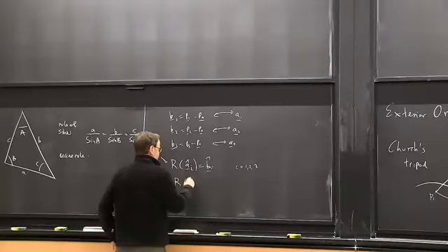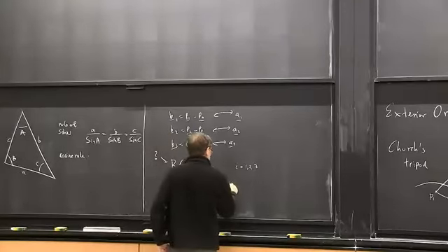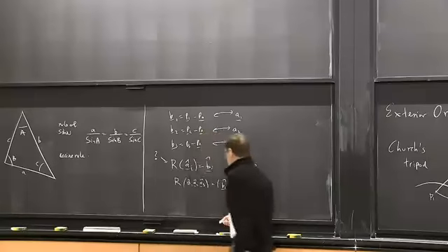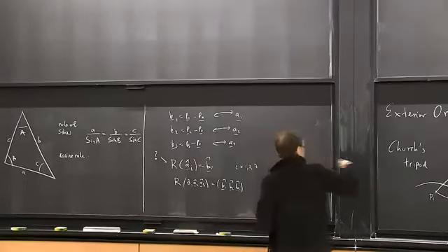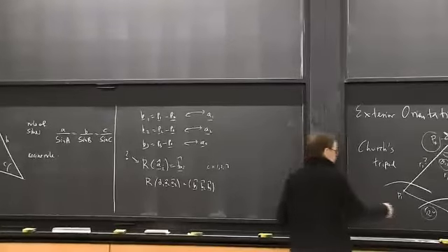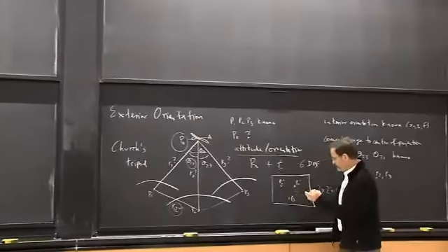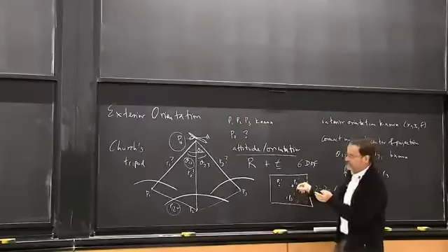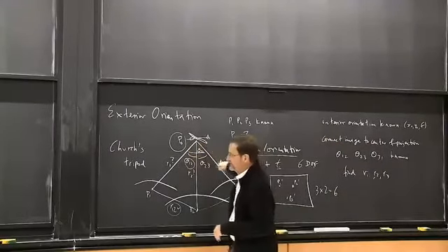Right, so we have... now all of these things are now known. We have the interior orientation of the camera, and so we know how to construct the 3 vectors from the center of projection to the 3 image positions, and we've calculated where P0 is. So we've got those 3 vectors.